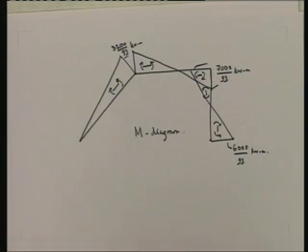here. Okay, so you saw the steps. The first step, identify the degree of freedom. Next step, write down all the force deformation relationships for all the members that are possible. Third, get the kinematic relationship between the member end deformations and the structural degree of freedom, displacement corresponding to the structural degree of freedom. Then use the virtual work equation and write down the equation corresponding to each structural degree of freedom. Solve for the displacement corresponding to the structural degree of freedom. From that, derive the member end forces.